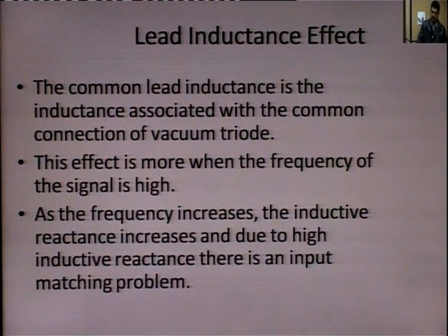But at microwave frequency, inductance increases, and as a result inductive reactance increases. You apply input to an amplifier, but a major portion of the input voltage drops across the inductive reactance. As a result, the gain reduces. I will show you in the next slides.